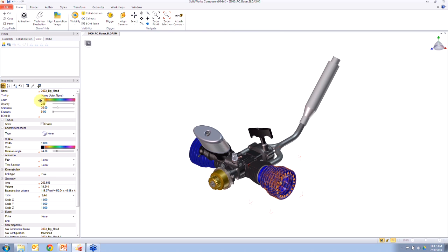What you need to understand is when you import models into Composer, it brings properties in from that original model source. We're going to assume that's SOLIDWORKS for now. So it's going to look at the SOLIDWORKS part, the SOLIDWORKS assembly, what colors the parts and faces are, where they're located in the assembly, how they're assembled together, and the metadata. That's the custom properties from the SOLIDWORKS file. So when you go into a SOLIDWORKS part and insert custom properties, material, part number, description, whatever you want, all that data comes into Composer as metadata, as a property.